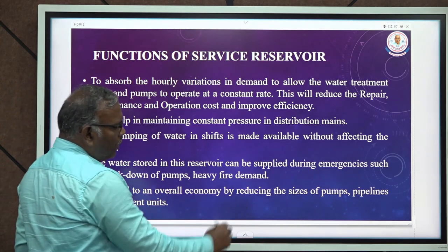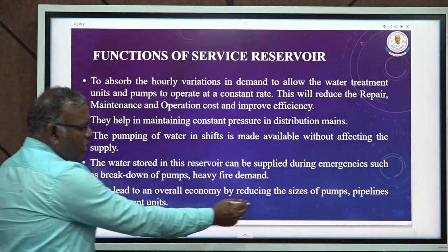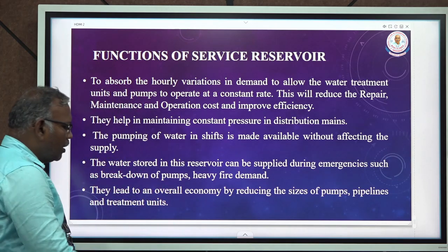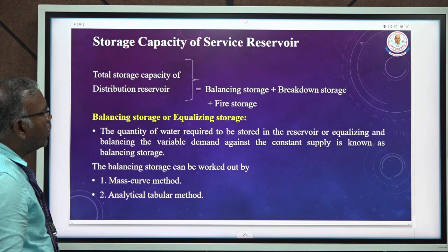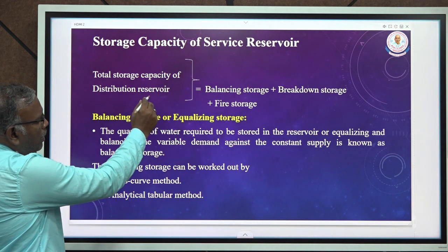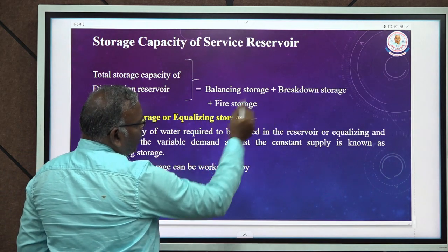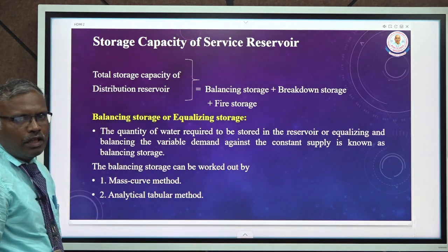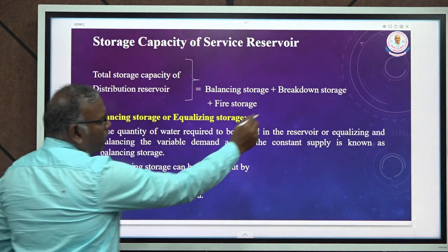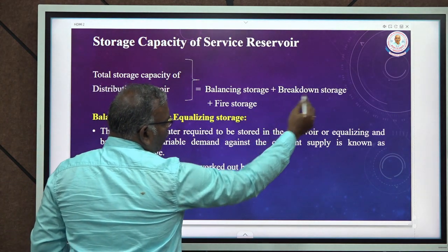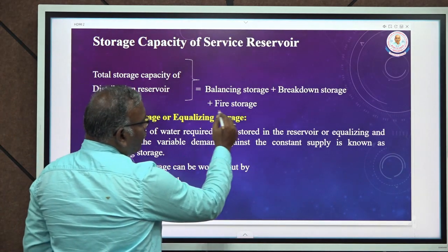Next, overall, due to the provision of this service reservoir, the size of the pumping main, pipeline as well as the treatment unit can be minimized. Okay, next, the storage capacity of a reservoir can be computed by finding the balancing storage between the supply and demand variation, as well as a particular quantity of water which is allotted for breakdown storage and fire storage.